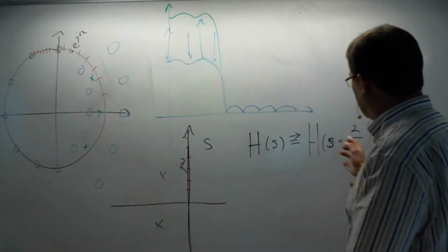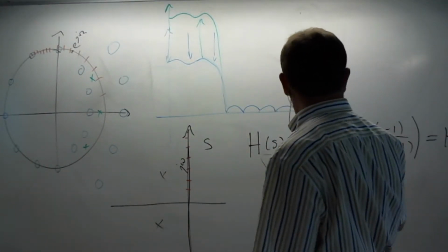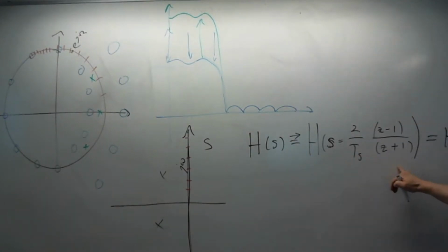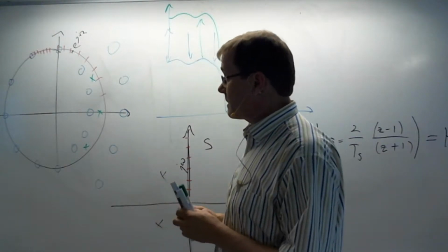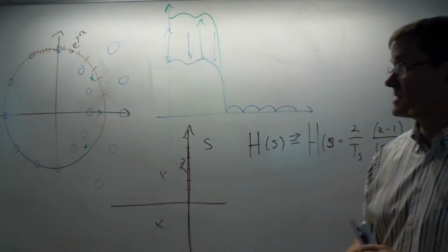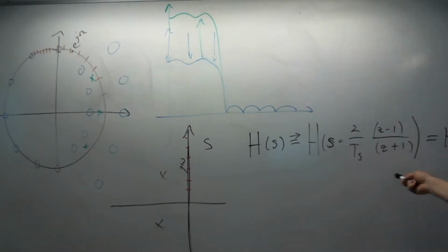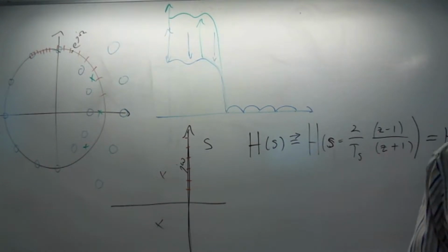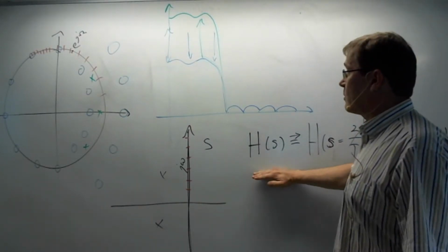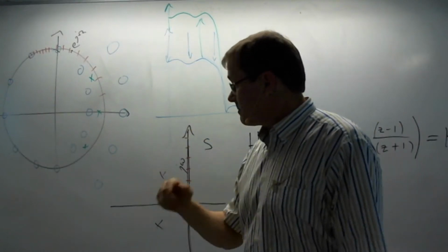Anyhow, if you have a natural system, usually the order numbers are quite small on a real natural system, up to say 8 or something like that. So you get an IIR system easily by using the bilinear transformation. Simple, effective, warps the frequency space. All right, that's one way to do the trick.